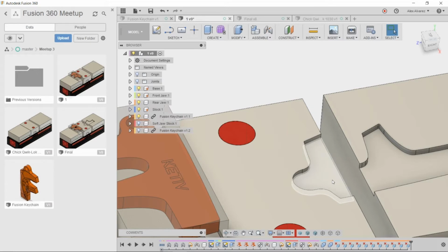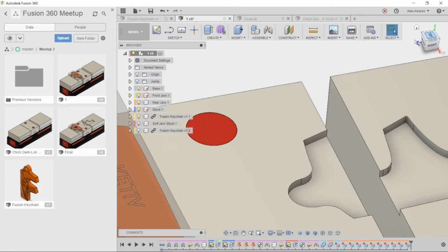Now you would want to do that because when you're going to be clamping your part in, sometimes these edges aren't perfect, right? So what's going to happen then is it's going to pinch your part. It might bring it up, right? So if you have maybe an 1/8 inch end mill, that's a pretty thin end mill going around your part, and you have the part lifted a little bit, you run the possibility of breaking your end mill if you have some sort of offset surface that you didn't account for, right? So we want to make sure that we provide some relief around these edges here.